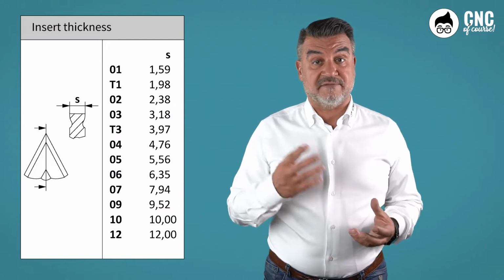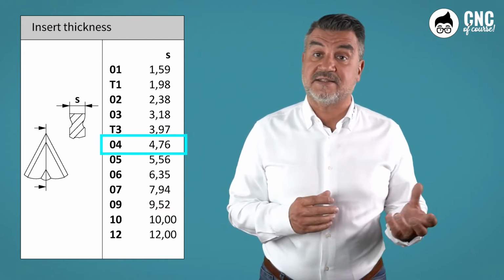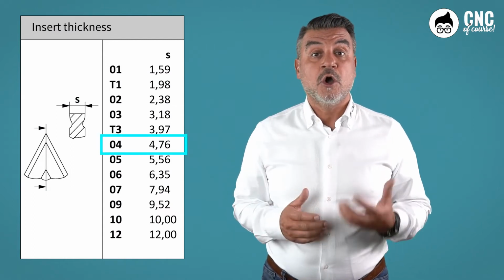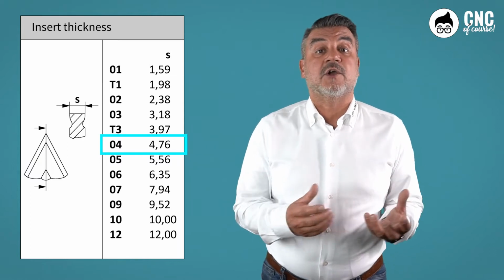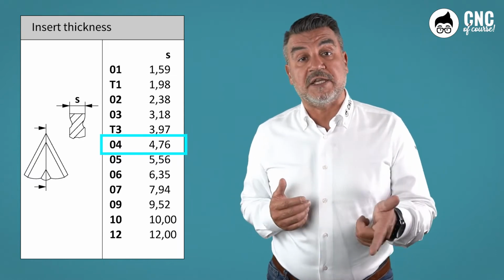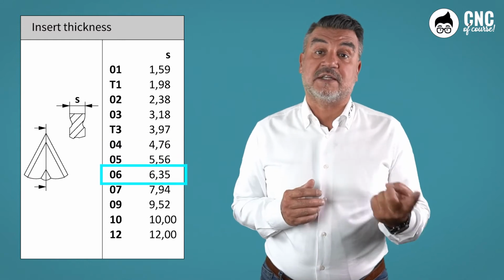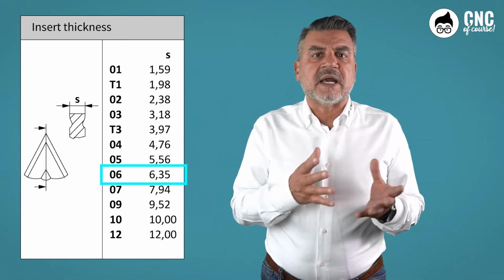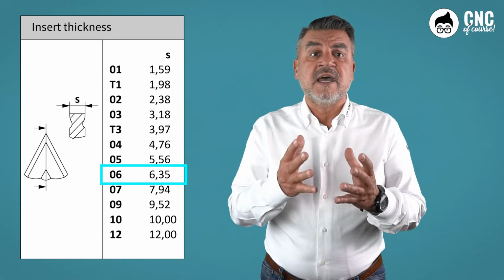Sometimes, it is therefore advisable to oversize the inserts in order to have a longer tool life, even if buying a larger insert would mean a greater expense. In fact, with the same chip volume, a 12-sided insert with a thickness of 4.76 mm like ours would not have as long a cutting life as its twin with a 16 mm side and a thickness of 6.35 mm, precisely because of the difference in the resistance section, which is almost 2 mm greater.